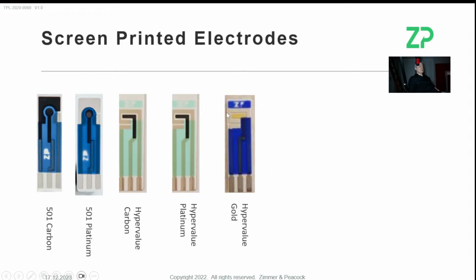Something I want to say about them is they're 25 millimeters long and 7 millimeters wide. So you are bigger than us, and that means that your manufacturing density is going to be quite low. I would really think about not pushing on something quite so large. If you look at the answer to one of the previous questions in this slide deck today, I might definitely cover the fact that if you can keep things small, then you'll definitely keep the cost down.